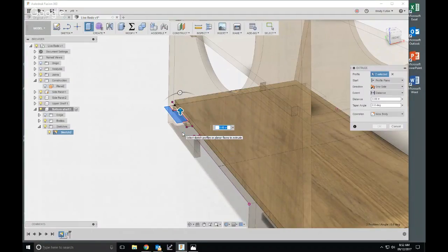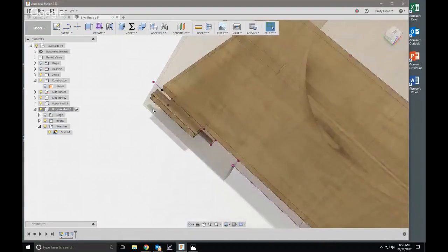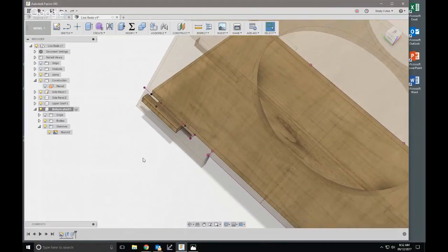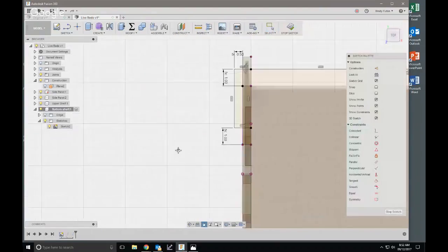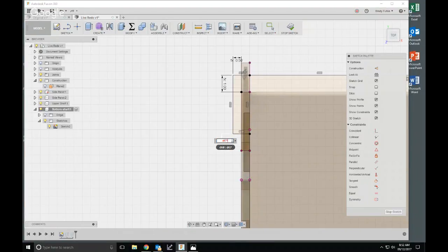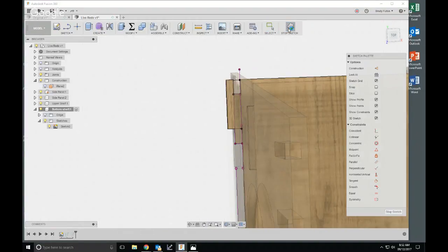And again, the reason I'm doing it this way will become more clear once that works. But then we'll do this right. So let's go back to our sketch. I'll show you something. If we do this, you've got 0 clearance. Once you pull this board back, it won't slide into this slot very well. So what I want to do is go that times 1.05. We have 5% bigger just to give us some clearance.